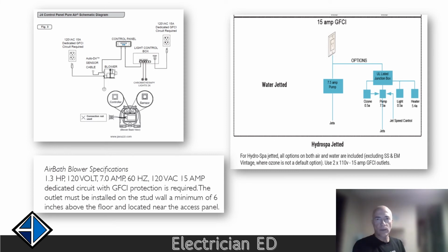Hydro massage tubs are permanently installed bathing tubs with pumps and piping systems for recirculating water, usually with other optional equipment as well. They differ from spas and hot tubs in that they are designed to drain their contents after every use. This difference also puts them into a different category in the NEC's view. While spas and hot tubs only require general purpose circuits, hydro massage tubs must be placed on dedicated circuits according to the NEC.